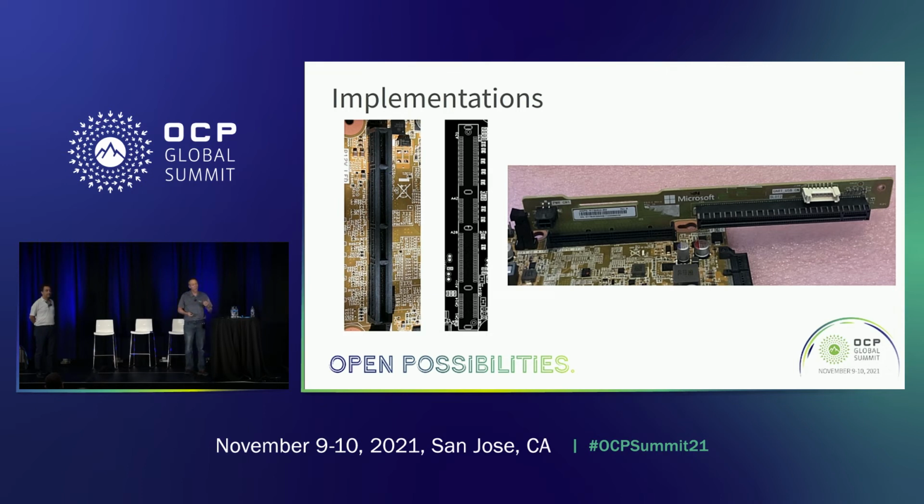What we wanted, and formulated a number of years ago working with EDSFF, was an ecosystem in which this connector can accommodate not just the signal integrity requirements of tomorrow, up to 32 gigabits per second or further, but can also plug in PCB boards, in terms of cards, or risers that are very popular, or cables. That was the key: getting to something that I could plug PCBs and cables into, because now I've got an ecosystem in which I can be a little bit modular, and from one motherboard, create multiple different use cases for my front I/O. What you see there is just an example of a riser board, but that connector also readily accommodates cables, as we're about to see.